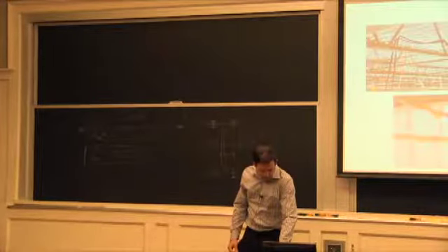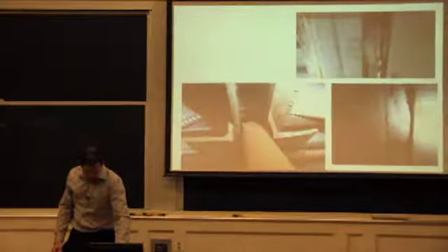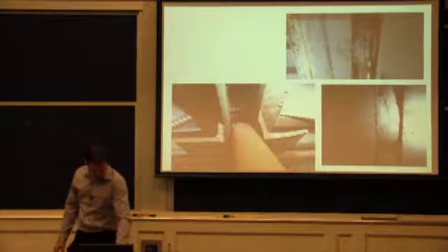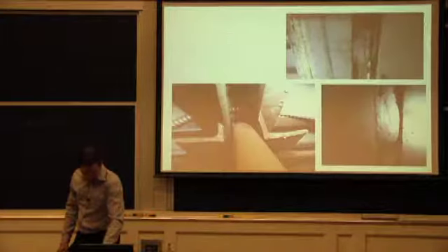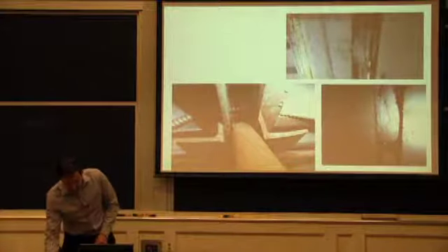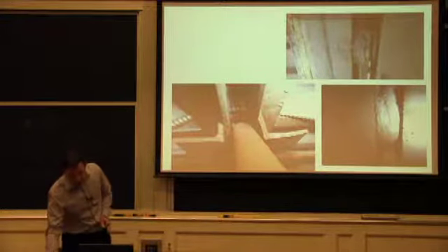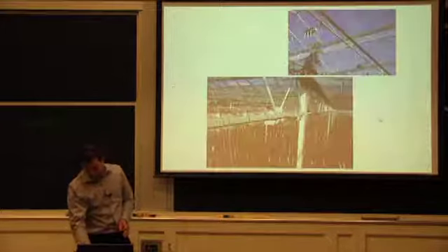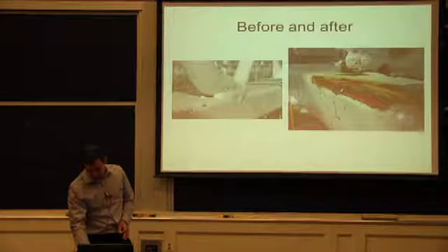So talking about weld fusion, maybe the last thing. These are some of the weld failures. You see here that it's just breaking off. We're looking at this location, but from underneath. The issue becomes, it shouldn't fail just like that, right at the interface between the angle of the joist and the welded bead. You're looking at the welded bead here, and it's just splitting apart. And it was very common. That's a big warehouse for tomatoes, a greenhouse, that I worked on.